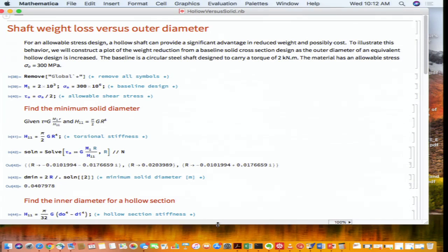So you have to divide this beam in this way, and you can write the shear forces and moments at this infinitesimal part, but the final boundary conditions would be two boundary conditions here for a beam in bending, two here, two here, and two here. So you'd have to connect the values present on the right end of this beam to the left end of that infinitesimal section.